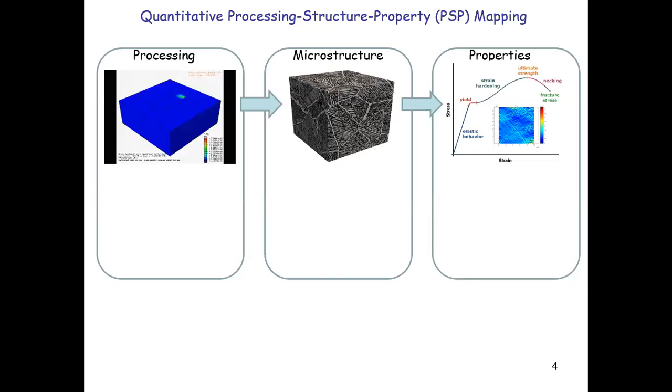But recently, people have developed this very advanced technique called additive manufacturing. So you don't have to really melt down everything. You can start with a solid state, and in this case, use a laser to locally melt or locally sinter the material in a solid state. And in this case, you can save a lot of energy and you can save a lot of material, right? Because you don't have to melt down everything. You just locally need to heat up the local material, make sure they form tight bonds together. And then you can directly make the shape you want by designing the path of the laser. Okay, so that's a very cool way.